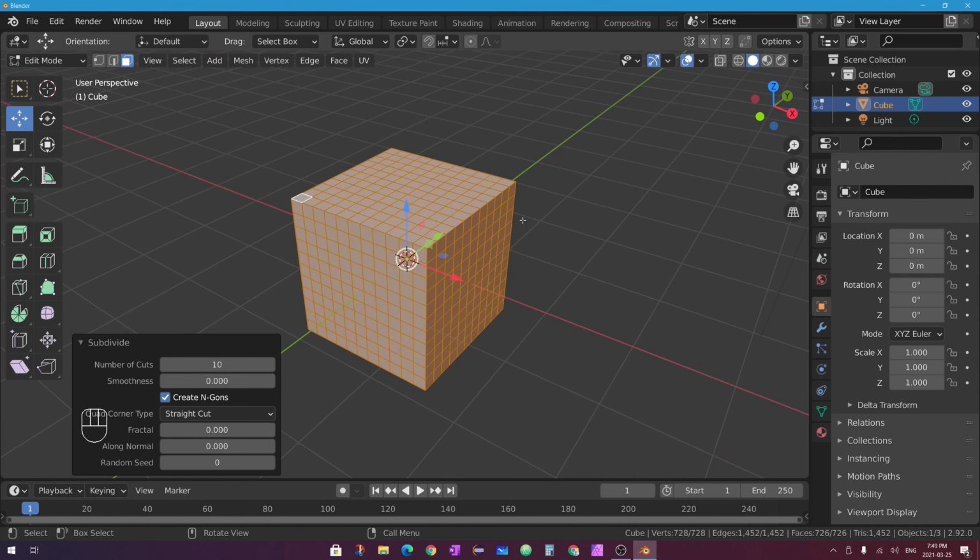You might think that if you want to make a very detailed mesh, you might want to start turning up the number of subdivisions on your mesh to a really high number to start modeling. That's not what you want to do. You want to start with a few number of faces, get the shape that you want, and then add more detail as you go. In this case, if I want to make a sphere out of my cube, the Subdivide tool has a smoothing option that I think is worth you seeing right now.